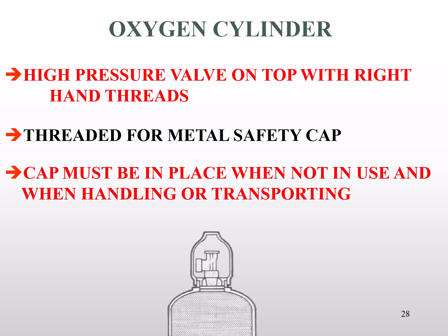I'm sure you can find many, many videos on YouTube of the end result. So two key points: right-handed hardware on oxygen equipment, and the safety cap must be screwed in place before moving the bottle in order to keep the transport safe.